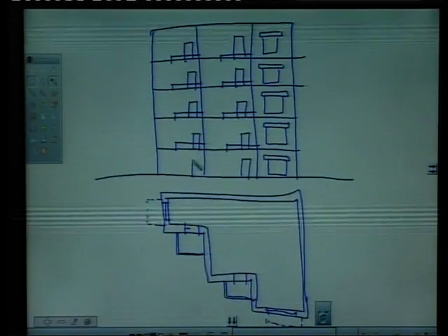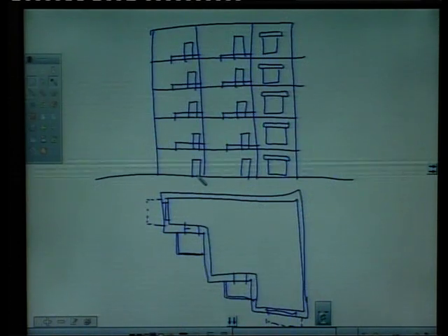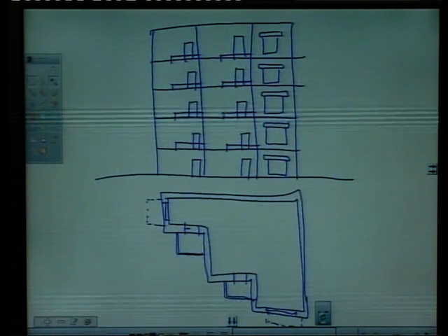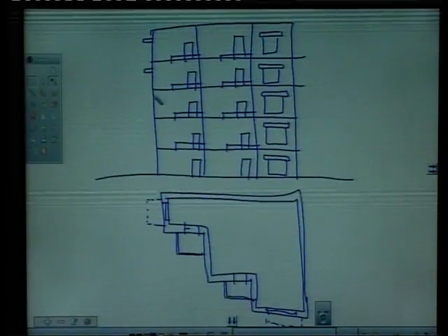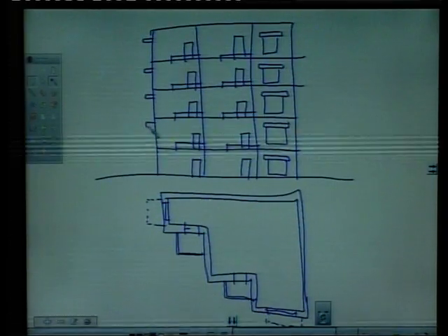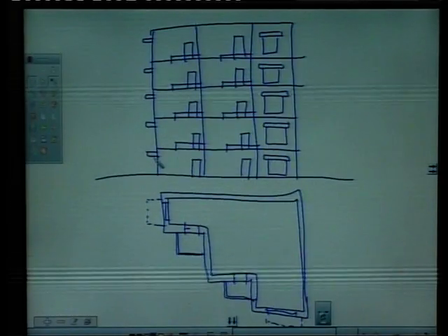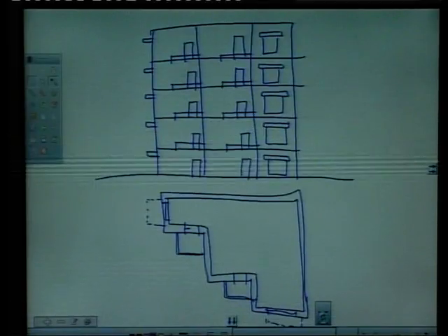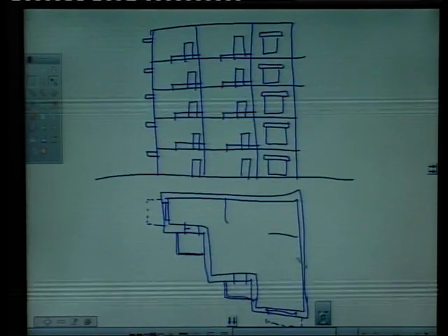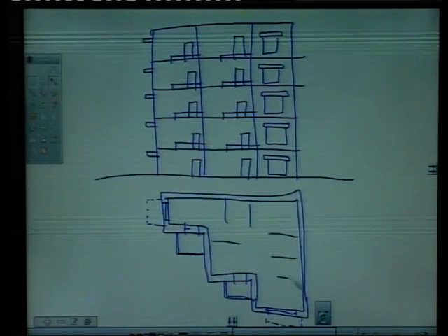When you practice these things, you should draw all this accurately and clearly. Say this is the chhajja projection of this window, and the window will not be visible to us, we will be only seeing the chhajja projections, right. So, this is the front elevation and this is the plan, and internal details we need not draw, right.